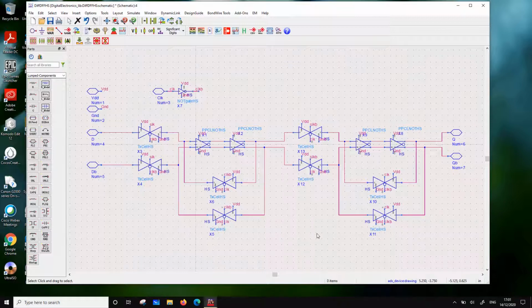Next thing is I'm going to make a 2x3 cell out of this. So that is going to be a prescaler for a PLL. So nothing is going to waste here. You might think it is very fundamental, but it will be used in the larger circuits. So you somehow make your libraries. Actually, you should also make a layout, so that you can develop much bigger circuits much faster this way if you make a library with the layout. This I recommend in Cadence. You can do this if you have library access to a PDK and Cadence.